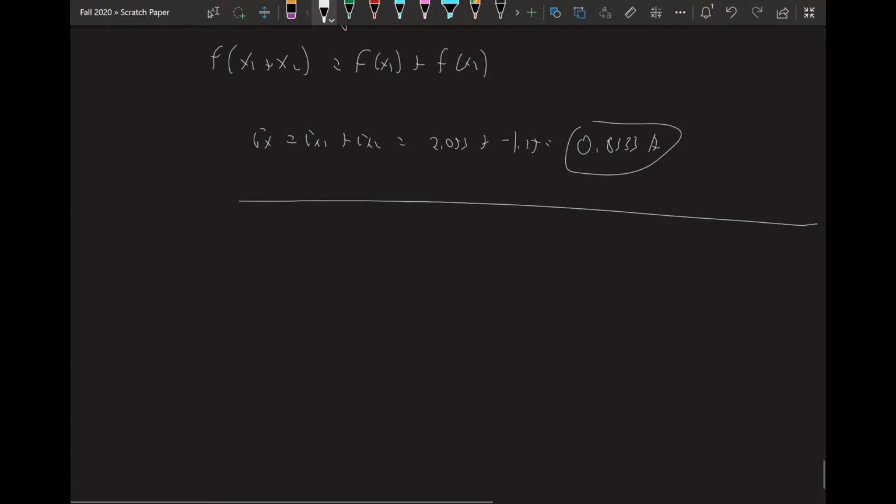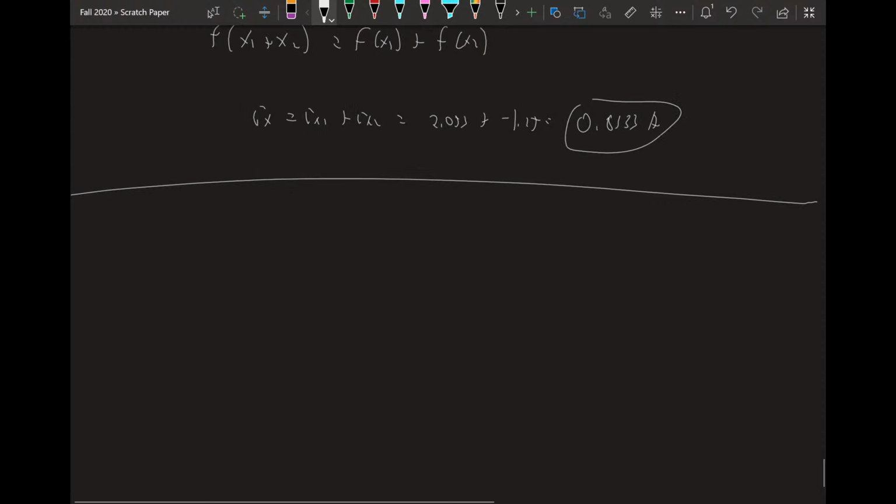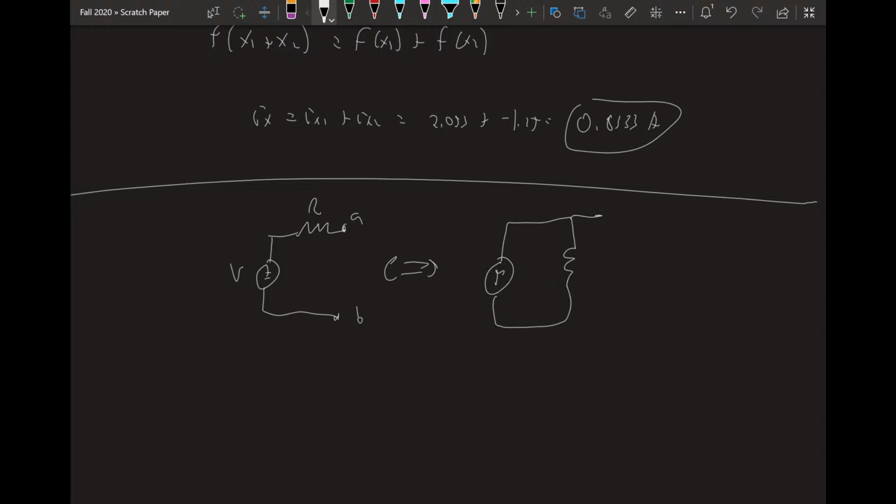Okay, so another helpful technique to help you solve circuits is going to be the source transformation. The source transformation is a simple theorem that says, let's say we have some circuit that looks like this, and these terminals A and B connect to whatever. It doesn't matter. What we say is that if we want this circuit to have an equivalent effect on those terminals, we can just turn it into something that looks like this. We can go back and forth here, and the effect over the terminals A and B is the same.